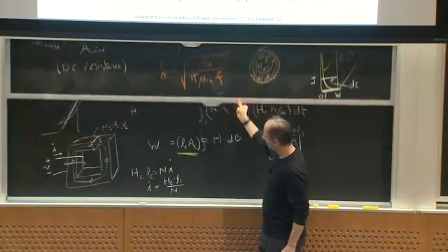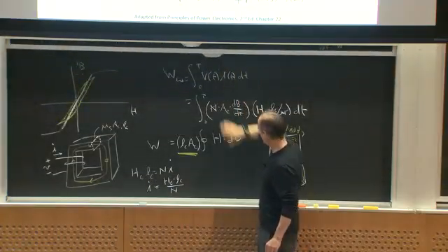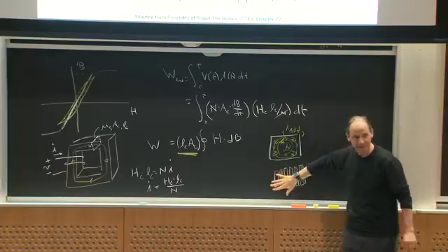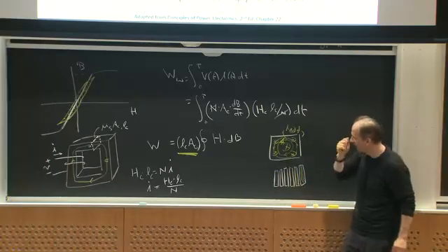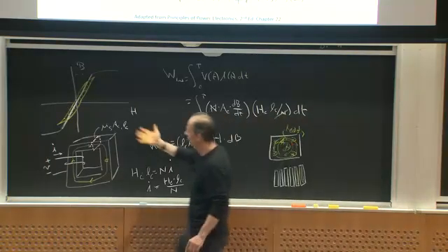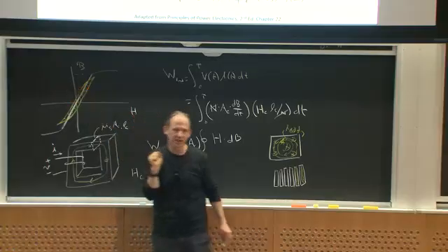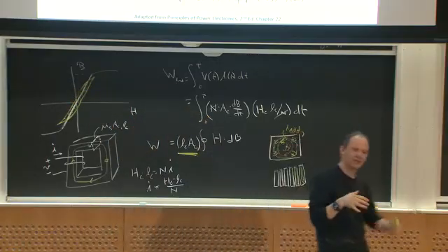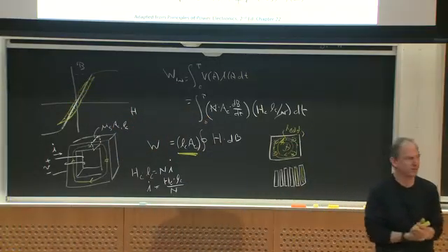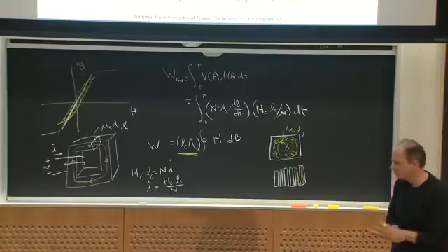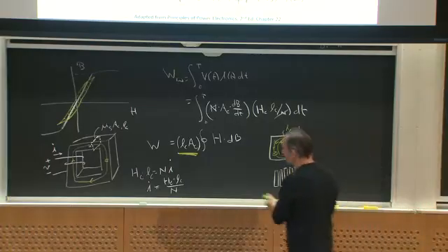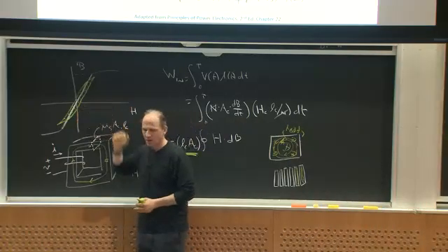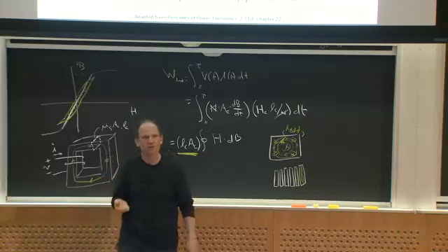I should say, I can fix eddy currents just by laminating. So then I'm left with this hysteresis behavior, but I said that hysteresis is in reality frequency dependent. And the truth of the matter is, it's not proportional to frequency. How do people treat it? They treat it rather empirically.